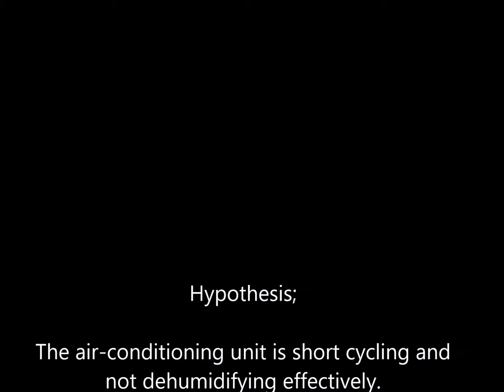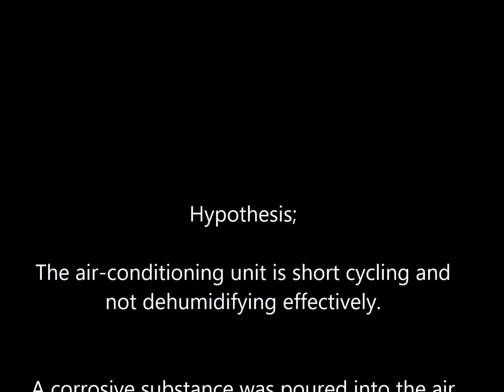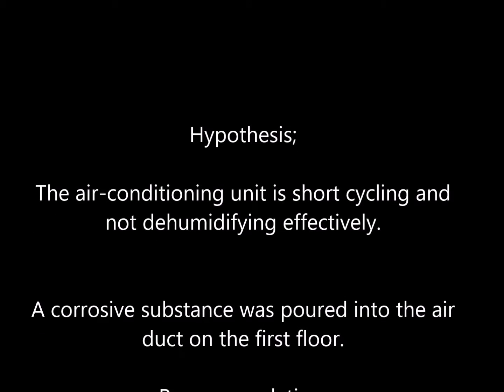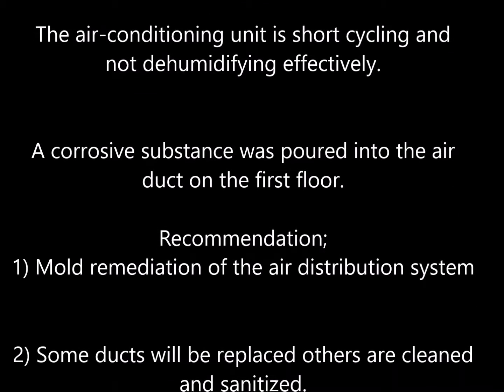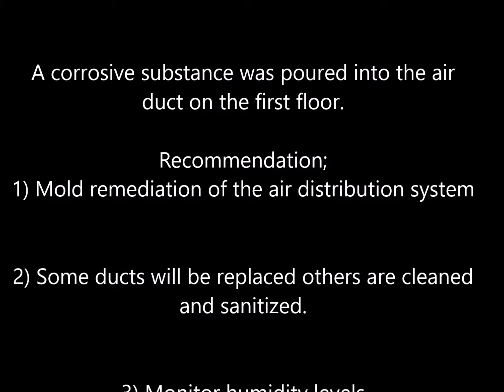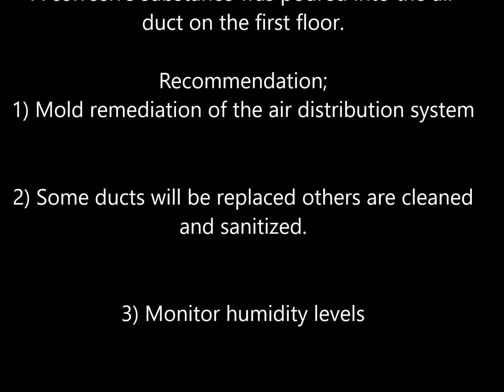To summarize, I suspect the air conditioning unit is short cycling and not dehumidifying effectively, and that this is the cause of mold in the ductwork. Also, a corrosive substance was poured into the air ducts on the first floor. This is most likely from the saltwater tank.